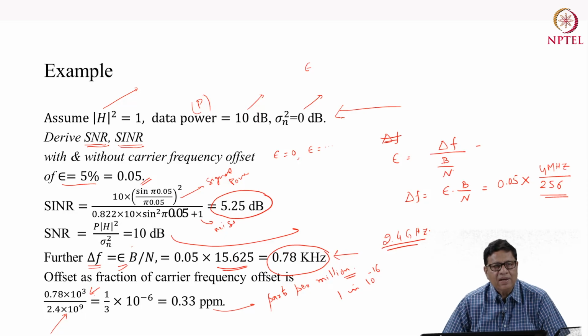So maintaining the local oscillator frequency and containing the offset is very, very important in OFDM. It's very challenging in cellular or RF communication, but that is not the case here because in our optical wireless or indoor communication, the user is not moving. So the only issue will come from drift in the local oscillator at the receiver.